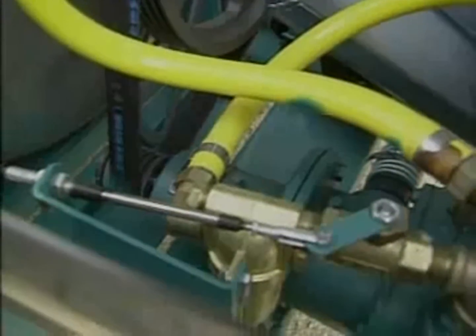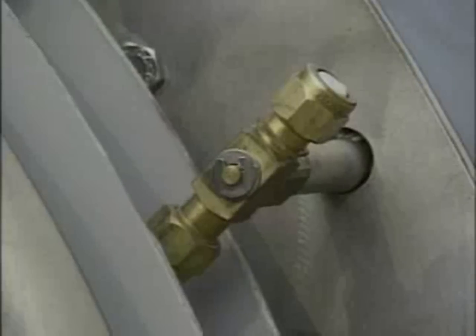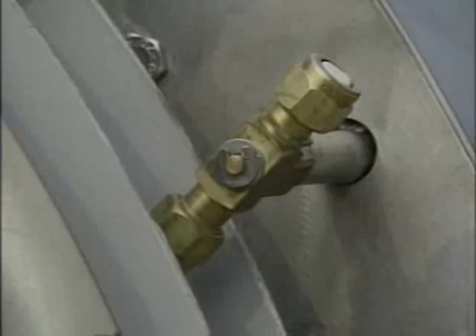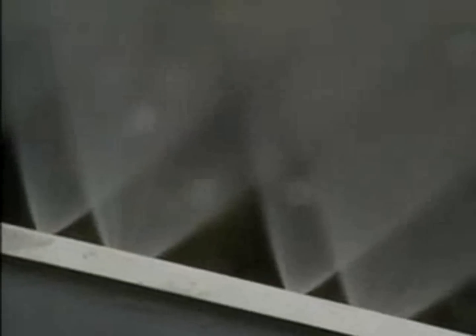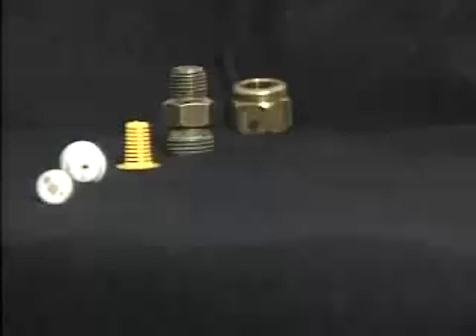Manifolds deliver the pesticide solution to the nozzles that are mounted on them in a manner that will deliver a certain spray pattern. On air delivery sprayers, nozzles meter the spray material into the air stream. By atomizing the liquid, the nozzle influences the droplet size and the number of droplets obtained from a given volume of liquid. The type and location of the nozzles also influences the spray pattern.